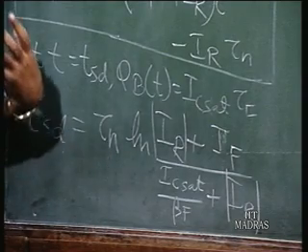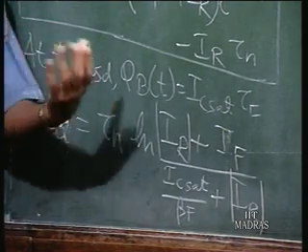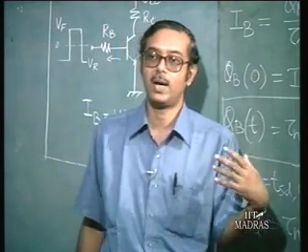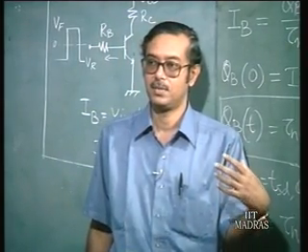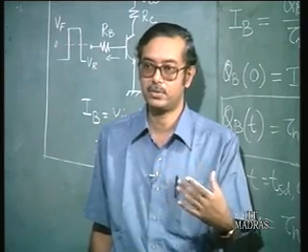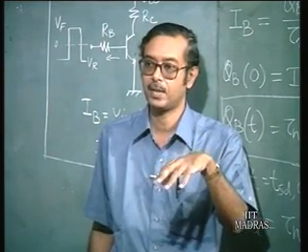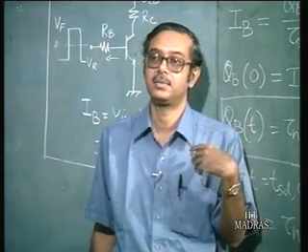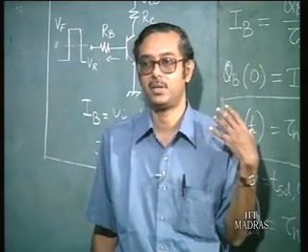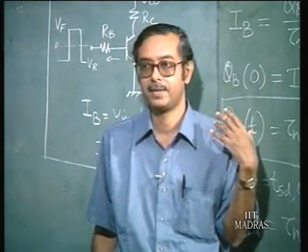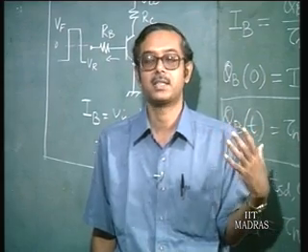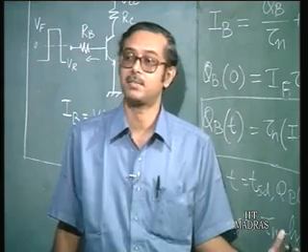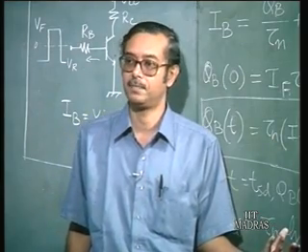But you cannot reduce IF because if IF is small, the on time is going to be high. So, you actually require a large forward base current to switch on the transistor faster, and you require an even larger reverse current to switch off the transistor faster. Okay. IR must be greater than IF in order that TSD, the storage delay time, is small.